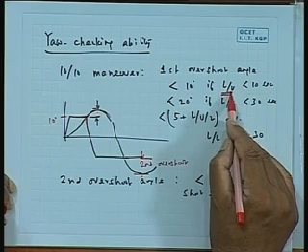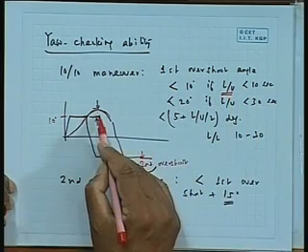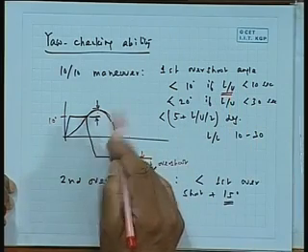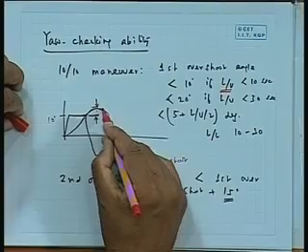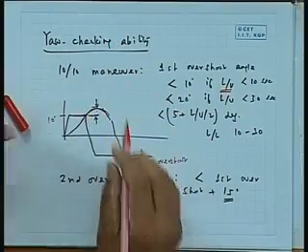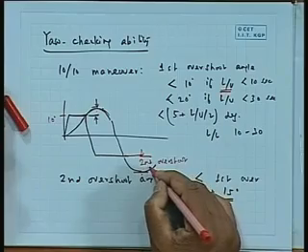When L by V decreases, then you must have a smaller angle, lesser overshoot, because otherwise the heading is less, but the yaw angle will be more because it's less time to go up. So it kind of restricts the path width basically. So this is how they have given it, because you want this overshoot angle. First of all, the criteria is with respect to the first and second overshoot angle.